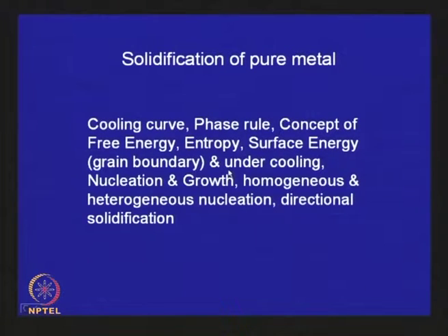We will also explain why for solidification to proceed some amount of undercooling is necessary, and the process of solidification is a time dependent process. There are two steps. The first is called nucleation, when a certain number of very small nuclei of solid will form in the liquid. We will look at the energetics of nucleation, and thereafter there is a time dependent growth process. The former is probabilistic, stochastic in nature, whereas the latter is deterministic, it will follow certain growth rules.